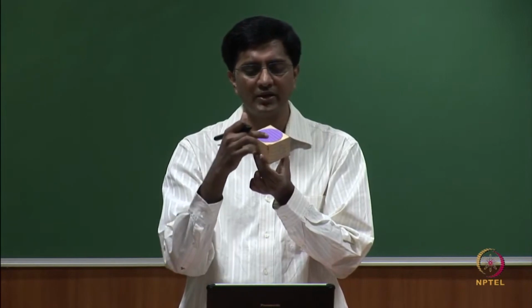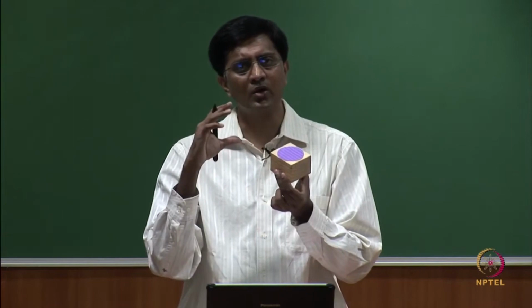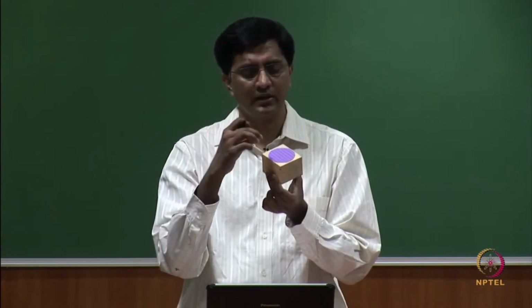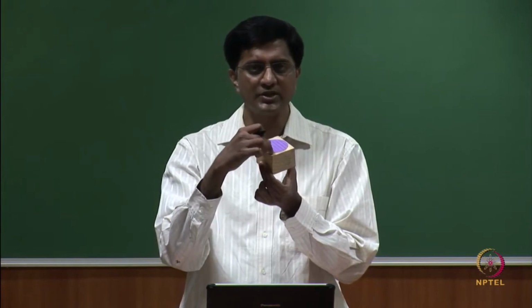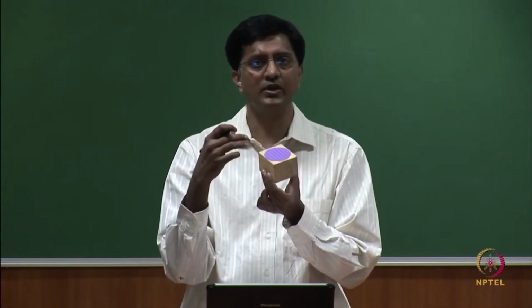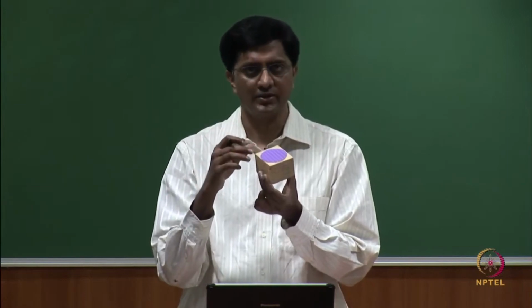Similarly, this angle of 90 and this angle of 90 are what we see as 120. This is called distortion of the view. To be precise, we are distorting these angles. In the true sense, this is 90, but the way we depict it on the drawing sheet is 120 degrees.